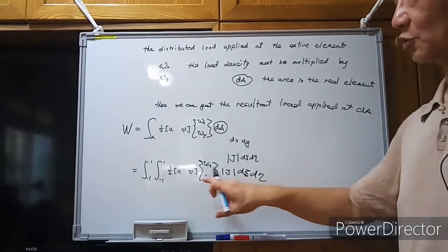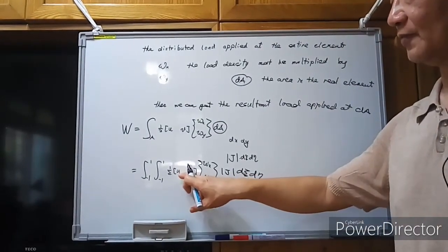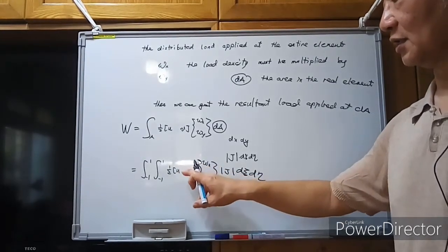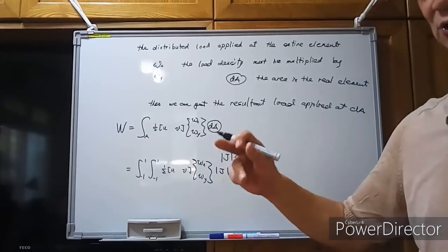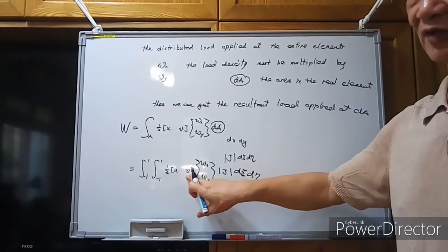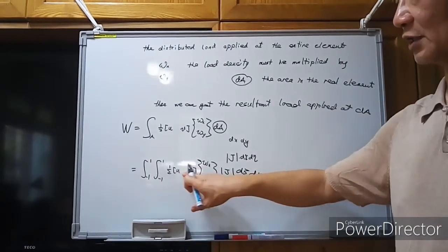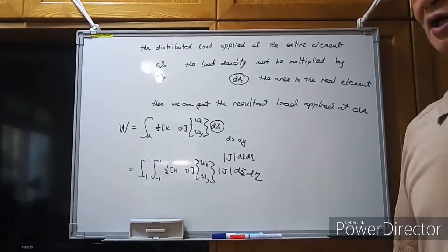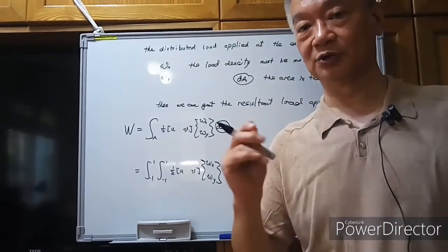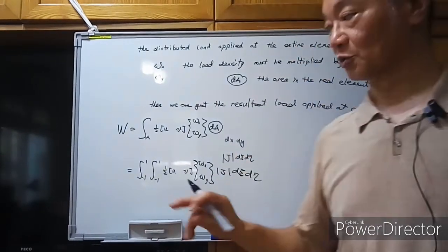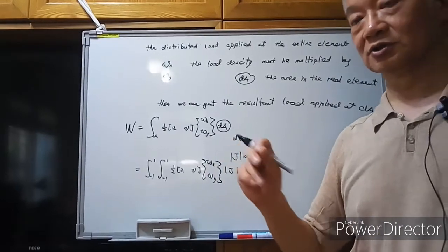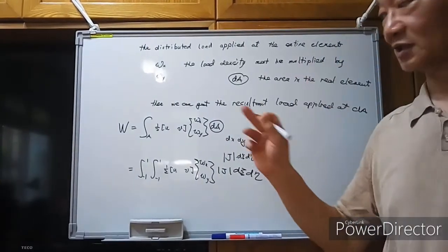The function values, the matrix or the scalar, which is a function of xi and eta, it will be the u and v values. And when we calculate the u and the v, part of the formulation uses the unknown nodal displacements. So when we calculate the u and v inside an element, we need to use the nodal displacements of this element.